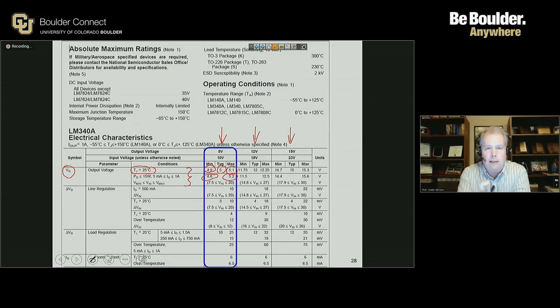you're basically eating into your noise margin or your margin a little bit in your design, because your processor will be spec'd to operate at a certain level. And if we reduce the output voltage, we're maybe eating into the amount of voltage noise that we are allowed to have on our voltage rail. But because of margins, it's still going to be fine. Even if we get a component anywhere in this range, we'll still be able to use it just fine.